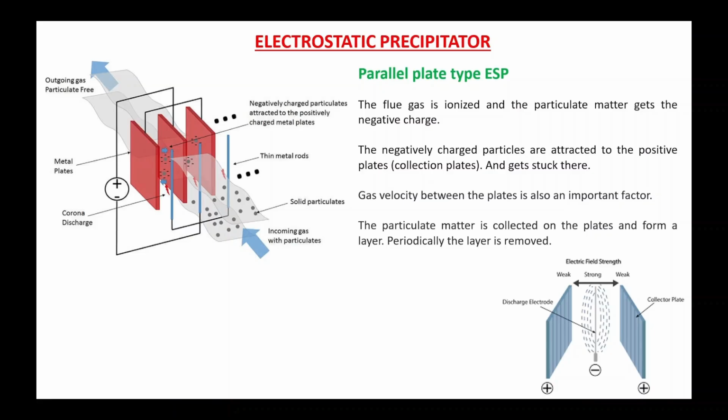Due to this electrostatic force between the positive and the negative charge, the particulate matter in the gas gets removed from the gas, and it gets collected on the collection plate.